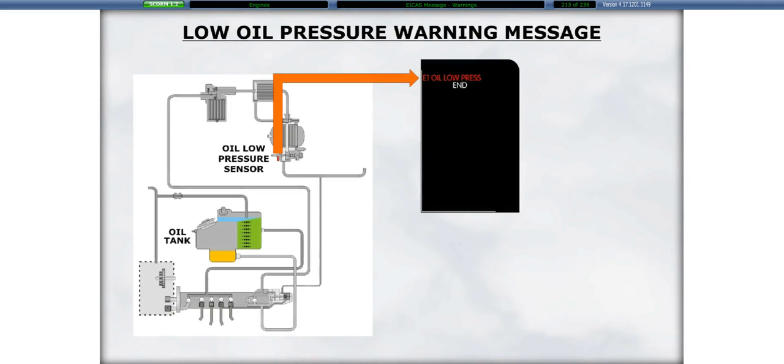An Engine 1 or 2 ATTCS no margin warning message indicates that the associated engine has no ITT margin to achieve the TO1 thrust if the ATTCS is triggered. An Engine 1 or 2 oil low pressure warning indicates that the oil pressure in the associated engine has dropped below 34 psi while the engine is running. It can also indicate that the respective pressure switch has failed in the closed position when the engine is not running.